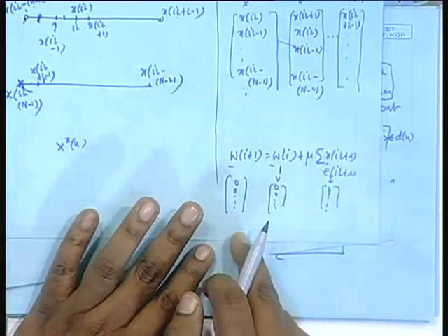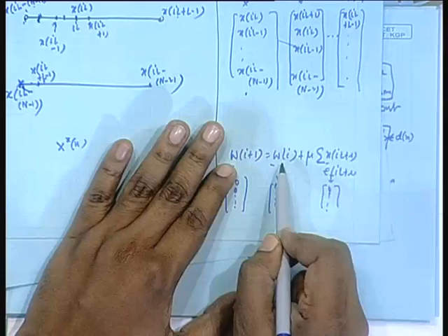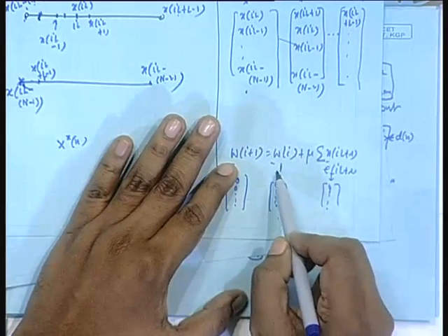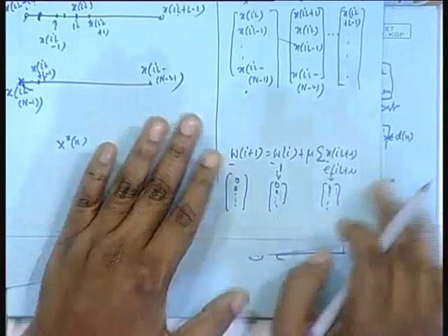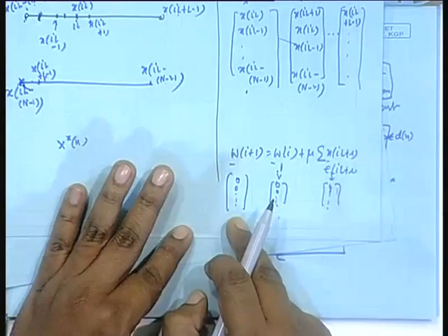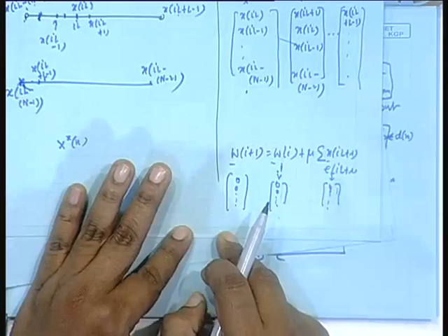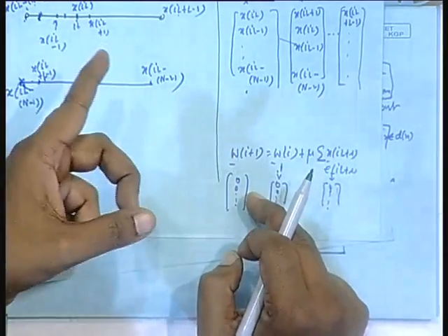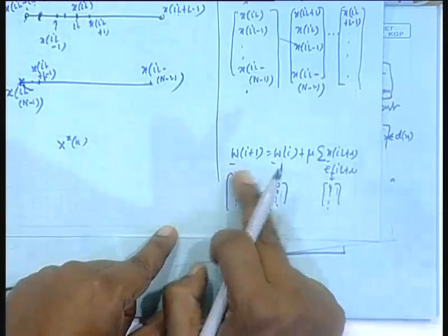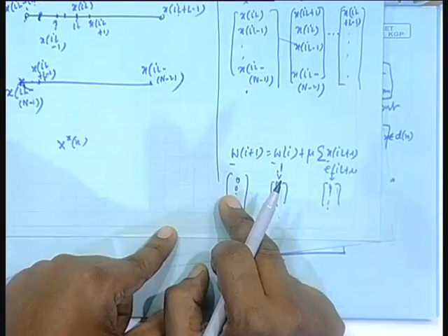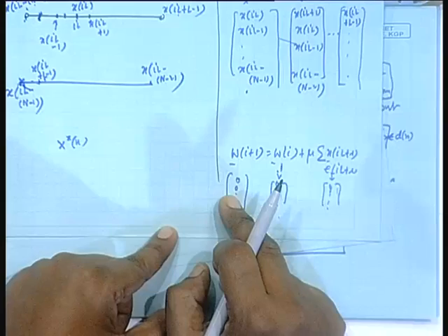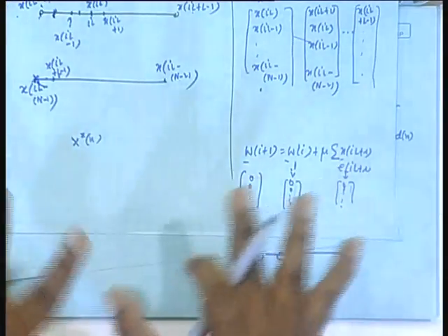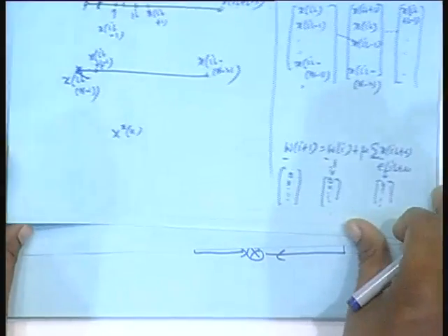Are you following what I am saying? This vector as it is, length n, I will have L minus 1 zeros in the bottom. If you add them naturally here also the last L minus 1 positions will be 0. That suits me, because if I take the DFT of that it can be used in the filtering part in the circular convolution, because there it was needed that the last L minus 1 guys should be 0. Okay, see how beautiful this thing is, things are fitting in all directions.